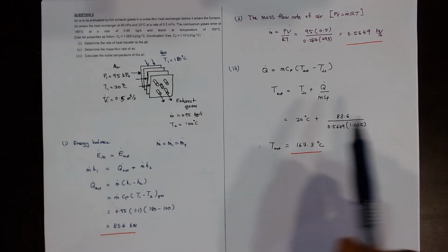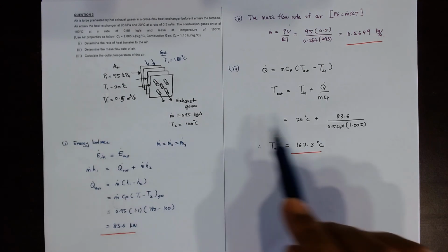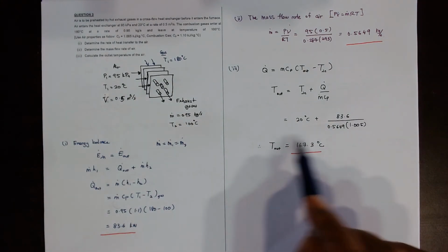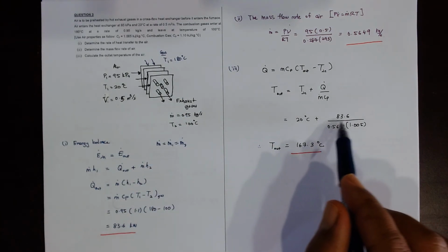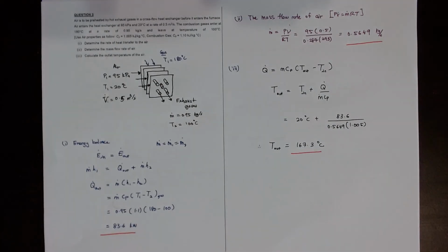Another thing is that, with 180 coming in and 100 degrees Celsius out, the answer should be between 100 and 180. If you forgot to convert, or directly converted into watt, you would get a value of 1673, which means your answer is wrong. That is one way to check whether our answer is correct.